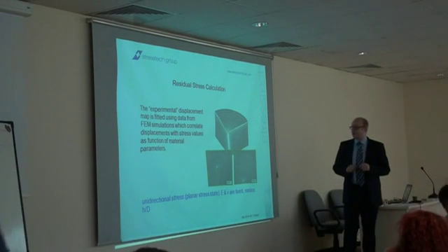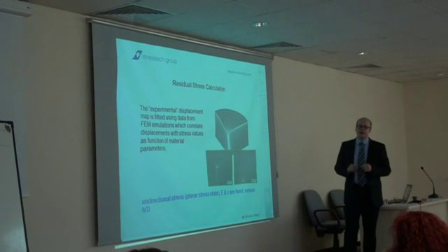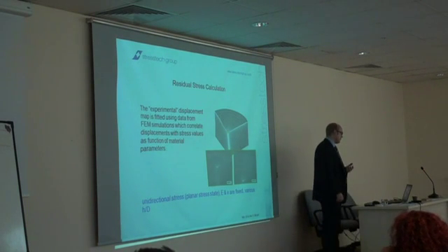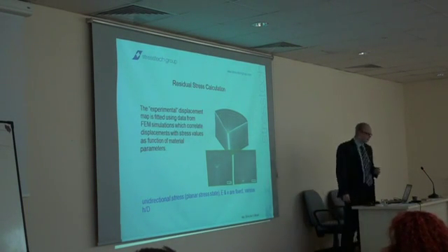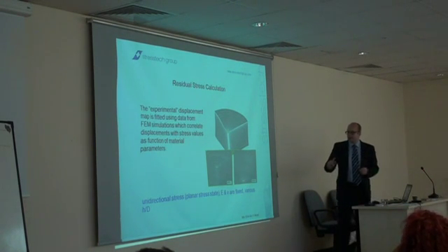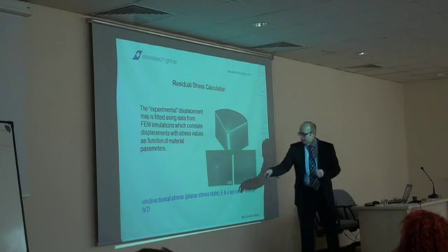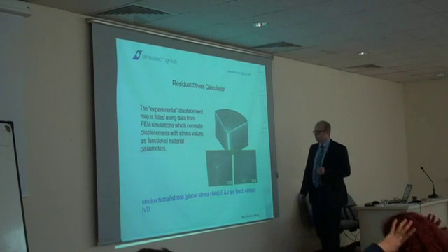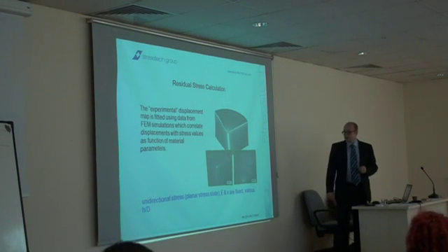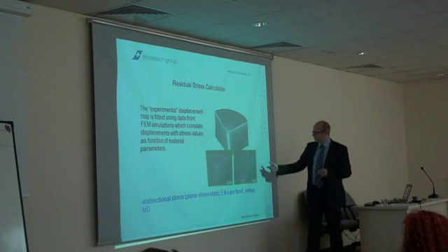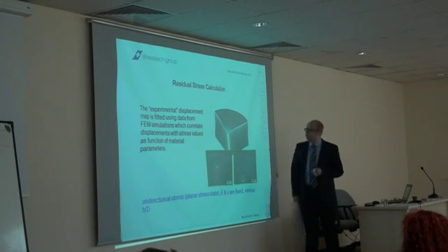And of course, we have to have some kind of finite element simulation behind the software. It's exactly the same as in traditional hole drilling. And again, you have to know the material parameters, Young's modulus and Poisson's ratio. And here is an example of height and diameter values.